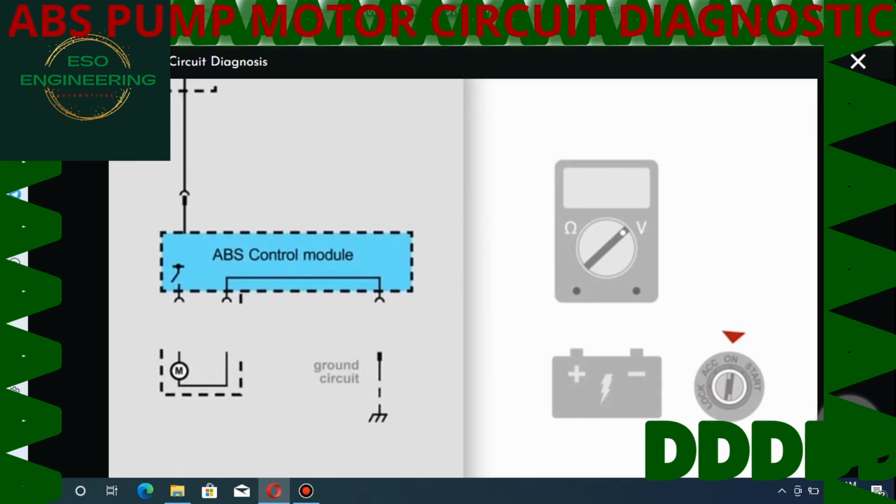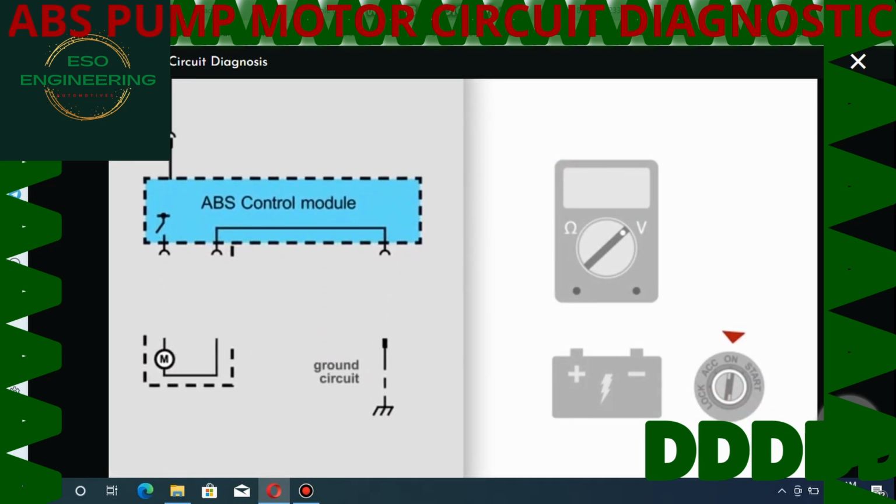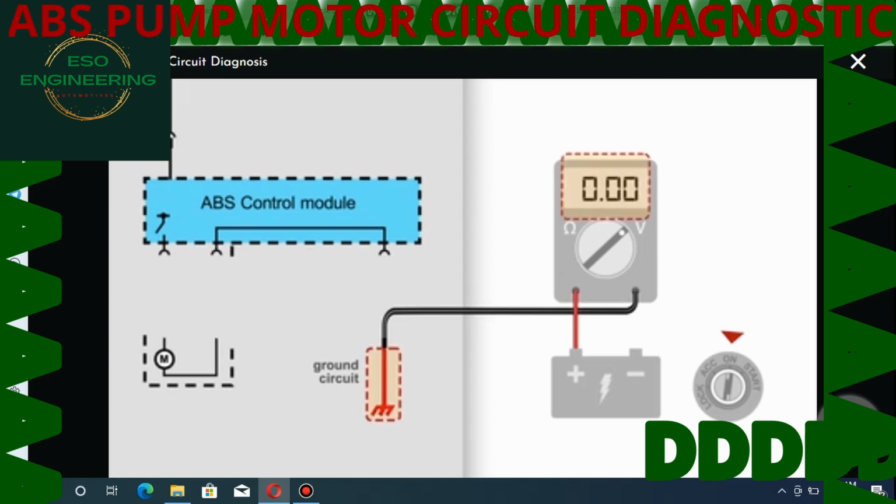Disconnect the module harness connector. To check for an open on the ground circuit, put one meter lead on the ground terminal at the module connector and put the other lead on battery positive. You should see 12 volts. 0 volts will indicate an open circuit. If this was the case, repeat the test on the chassis ground connection. If 12 volts is now displayed, then the open circuit is in the harness. If 0 volts is still displayed, check the ground connection.